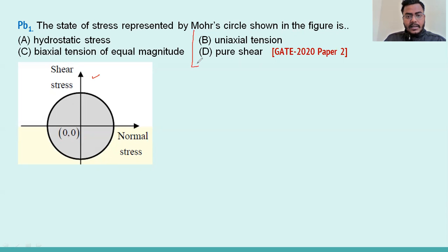First, let's discuss what is the Mohr circle. So Mohr circle is the graphical representation of normal stress and shear stress. If you want to calculate normal stress and shear stress at any point, suppose this is the element given, and there are different normal stresses acting, sigma x, and you want to calculate at this plane, that is at angle theta with the horizontal, sigma and tau.